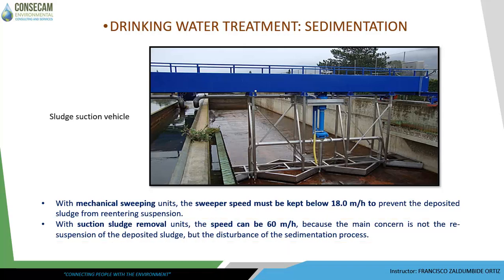In the different types of horizontal flow units, sludge or sediment removal can be done intermittently or continuously. The intermittent sludge removal system is used in small installations or when treating relatively clear water. For this purpose, it performs the bottom purges and every 6 months empties and cleans thanks to pressurized water hoses, since usually the sediments are compacted and transformed into a pasty mass that slips very difficult. For continuous sludge removal, the mechanical systems mentioned above are used.